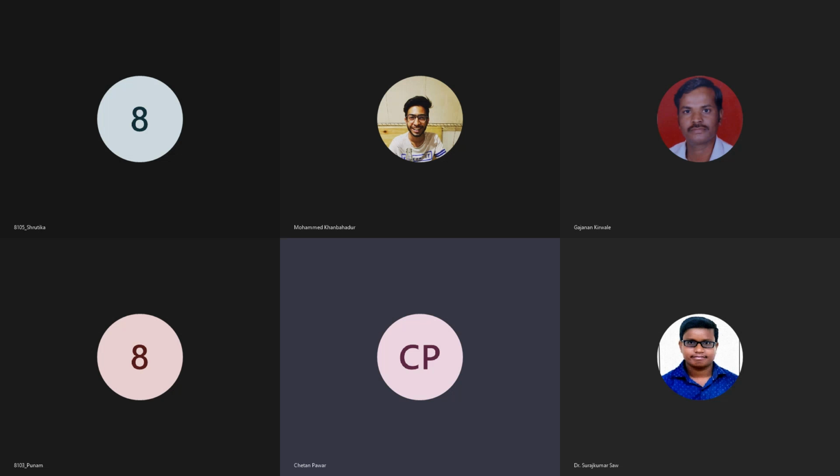Oh, wait, Shrutika. One more thing. I want to give the input here. I have just taken the pulse, right? But we have to provide this also. It's voltage 1, voltage 2, period, delay, rise time, hold time, and pulse width. Just provide the input here. Give the voltage level 1 as 1 volt, whatever you want. Voltage 2 as 0. Yes, provide the input. Type there, yeah, good.